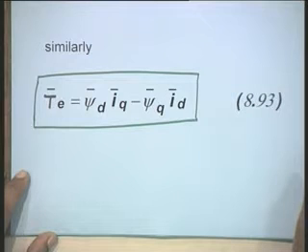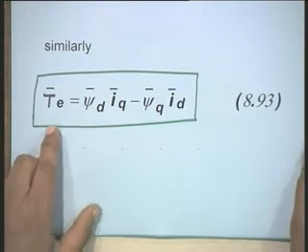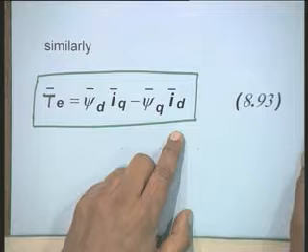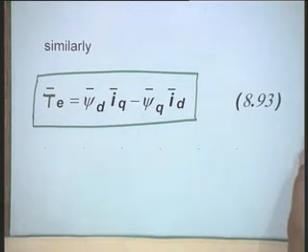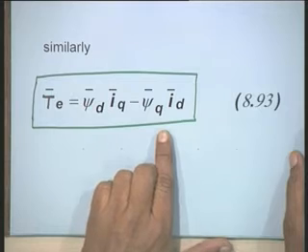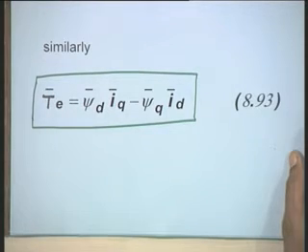Instead of calculating the torque in terms of 3 phase, we are getting the torque just by 2 values. The torque is computed in per unit using the per unit flux linkages and per unit currents. This expression is going to be used in our swing equation. In the swing equation we have to write mechanical torque minus electrical torque, and this is the electrical torque that will come in the swing equation. Okay.